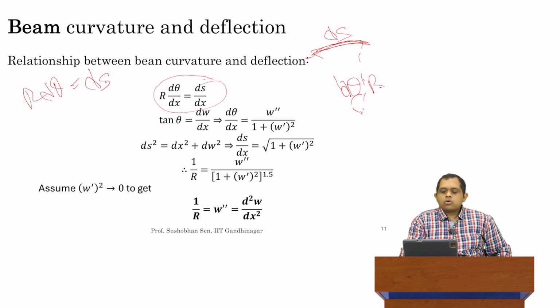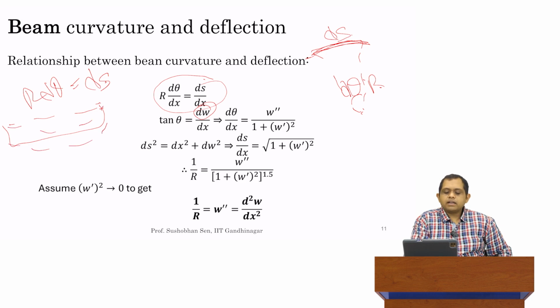Okay. Now, from here, we have to do a couple more calculations. One assumption I'm going to make here: I'm going to define this term W. W is going to be my transverse displacement. So if this was my original beam and my beam has undergone some amount of bending, at any given point, I'm going to define this displacement as W. If I take the tangent of theta, I can show that the tangent of theta is equal to dw over dx. You can derive it yourself. It's basically just from this triangle. It's relatively simple. But the tangent of theta is dw over dx.